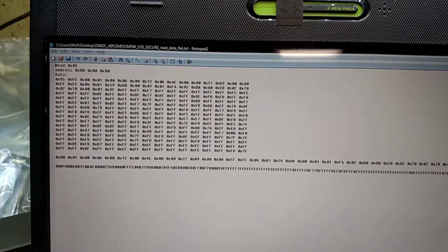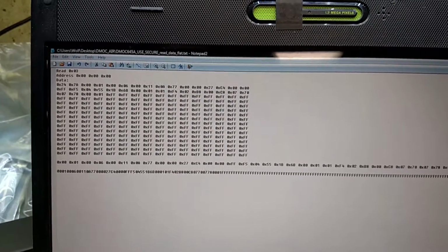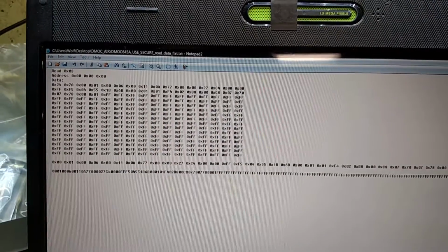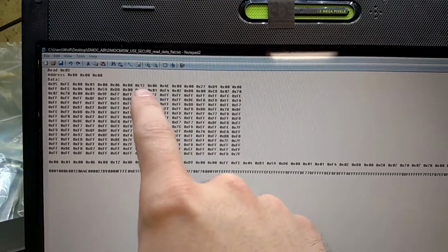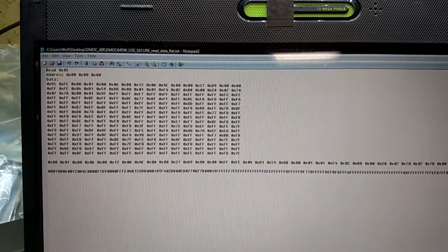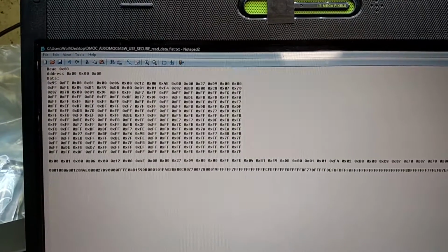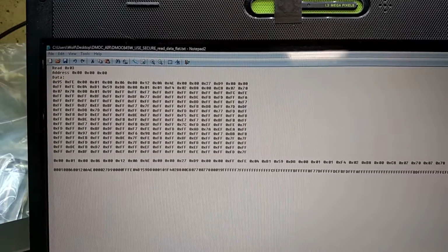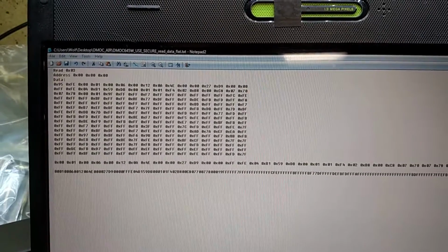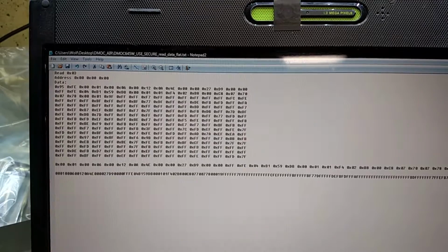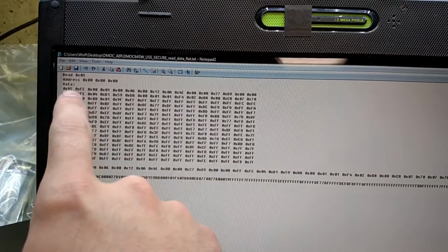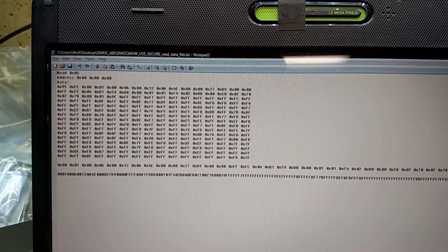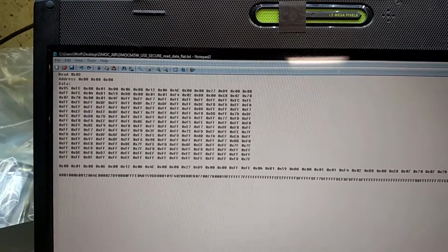In order to change this byte from 11 hex to 12 hex, we need to be able to calculate the checksum, otherwise it'll have a checksum error and it won't use it. And in order to calculate, we know it's a cyclic redundancy check because changing one bit caused a large change in the checksum. So we need to go and reverse engineer that.